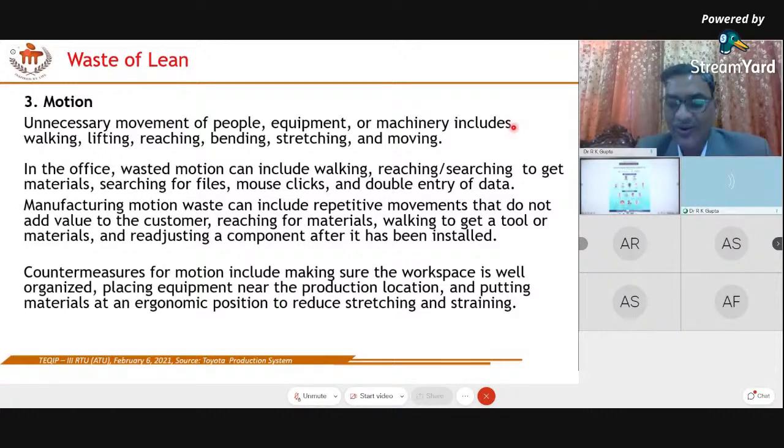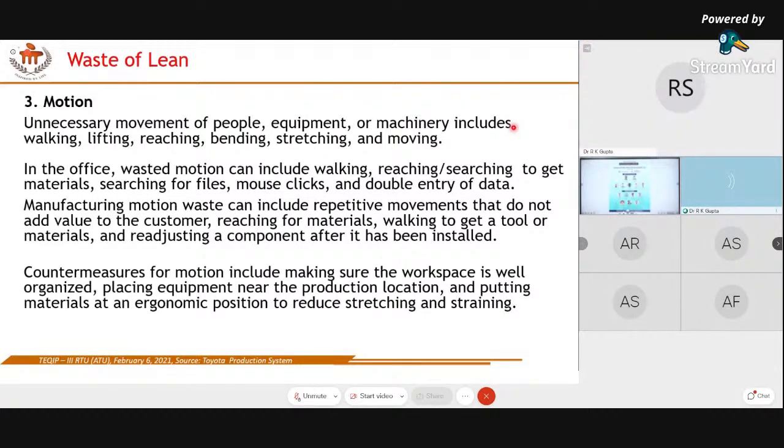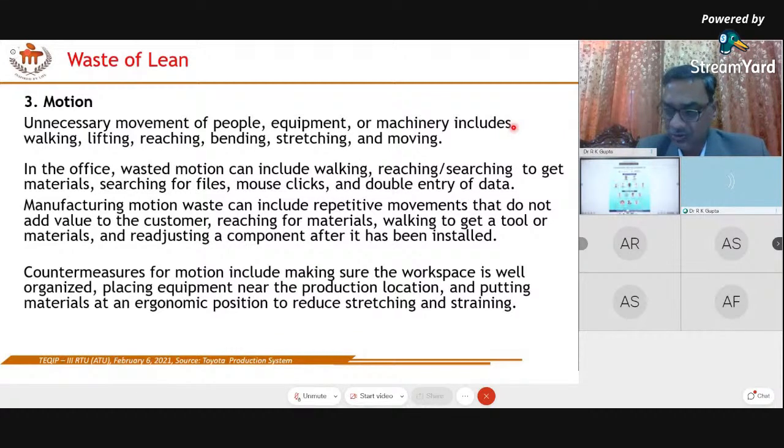So we have to adjust all these machines and our production on the basis of the takt time, so that the time taken between stations is even, and there is no waiting and no over-waiting, and no piled-up in-process inventories at one machine.